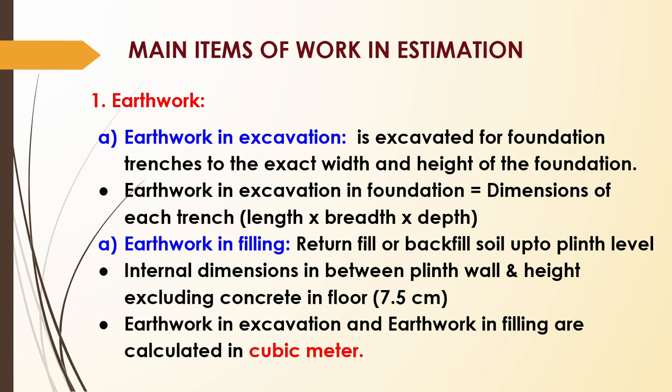In case of earthwork, we are taking the volume. How much amount of soil is taken out? How much volume of soil is taken out? That we will do. So that is calculated by length into breadth into depth of the, not the foundation, the trench which we are making. So that is earthwork in excavation.